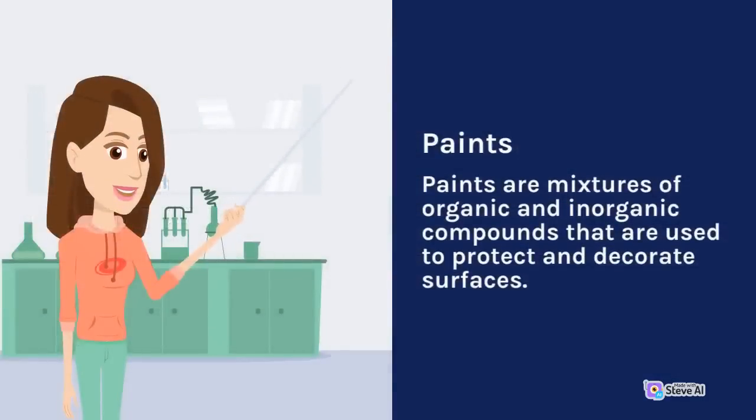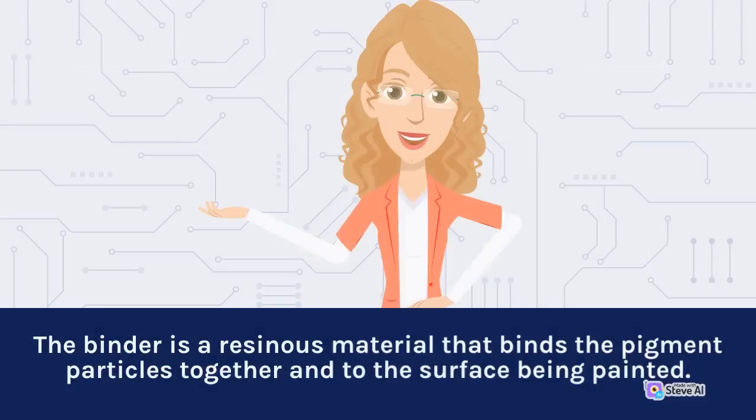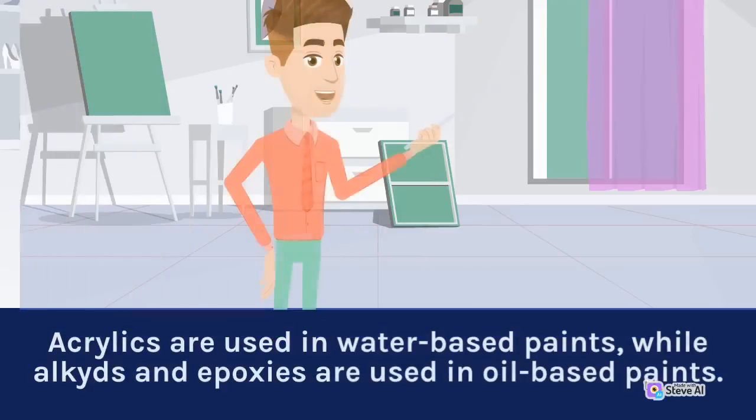Paints. Paints are mixtures of organic and inorganic compounds that are used to protect and decorate surfaces. Paints are typically composed of three main components: a binder, a pigment, and a solvent. The binder is a resinous material that binds the pigment particles together and to the surface being painted. The most common binders used in paints are acrylics, alkyds, and epoxies. Acrylics are used in water-based paints, while alkyds and epoxies are used in oil-based paints.